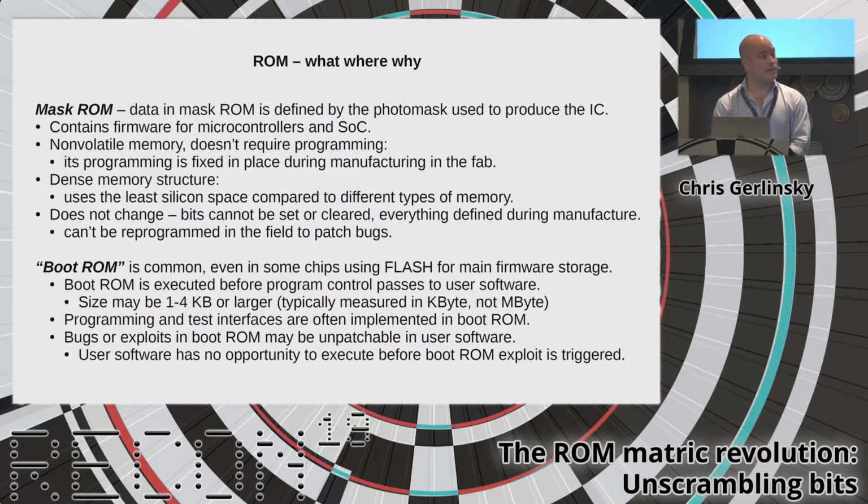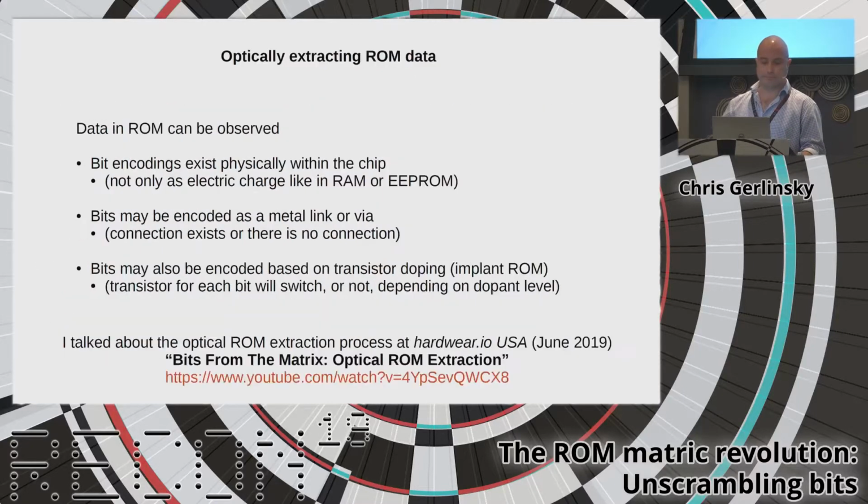A boot ROM is a common use of it. That's a ROM that will execute as soon as you reset a chip before it even runs any of the user code inside of the chip. These boot ROMs are usually quite small, like a few kilobytes, and they're interesting to look at because as an attacker, if you can exploit the boot ROM, then you have a way to exploit that platform without even worrying about the actual user software that's inside of that chip.